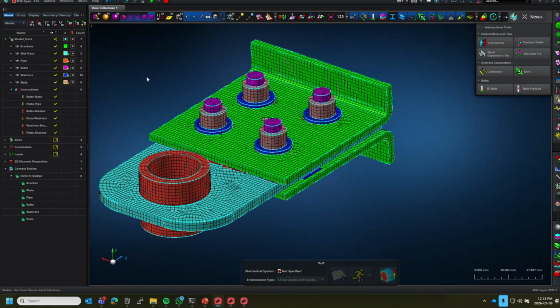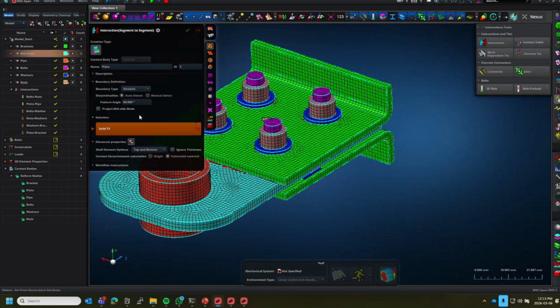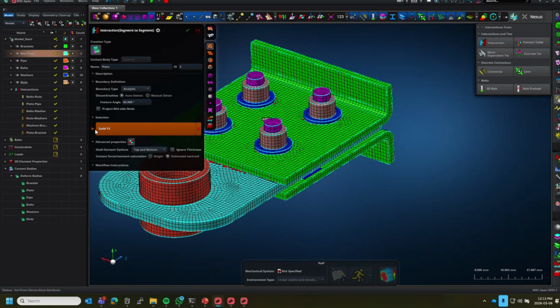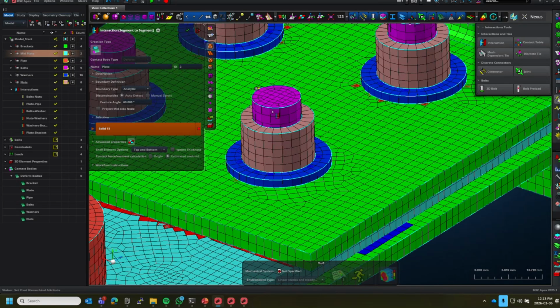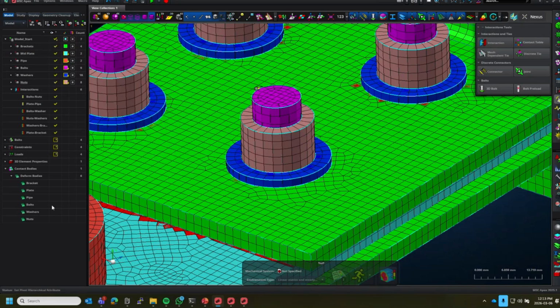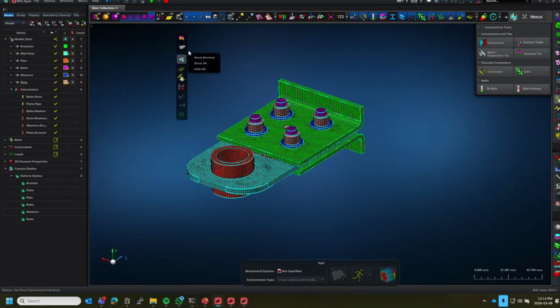And it's another important thing for contact. That has to do with analytical settings. So with analytical contact, if I open the arguments like the plate, it's set by default to discrete. If I change this to analytical, instead of making contact on the element faces, it fits a spline through the faces. So along that edge, it will be a smooth shape. So I can do that for that one. And then I go through the list. So the plate needs to be, because there's a curved interface.